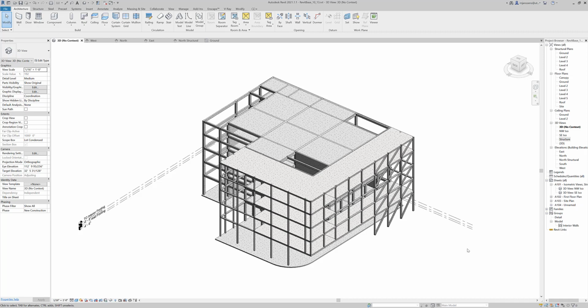The next part of our foundation, if we're going down from the slab, is the grade beam. The grade beam runs the perimeter of the slab, and it helps with load distribution, but it also mainly helps with the frost depth of the building. If you're in a really cold location, this will probably get deeper, and a lot of you already have basements in those cold locations, so you don't really have to worry about lengthening the grade beam per se. But a standard grade beam depth is about 36 inches.